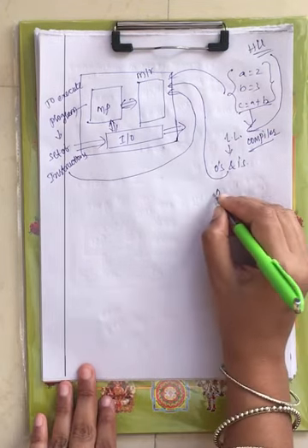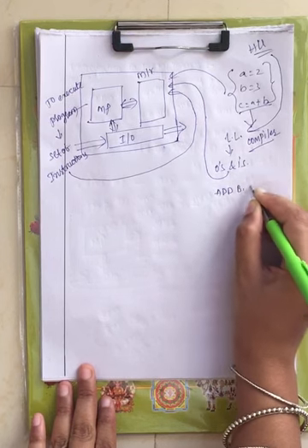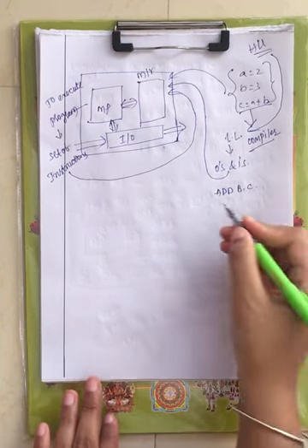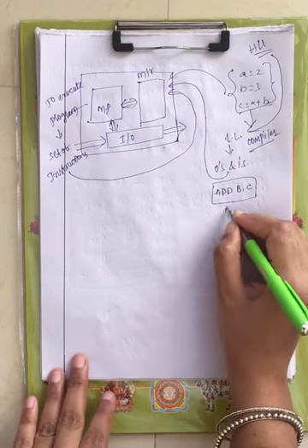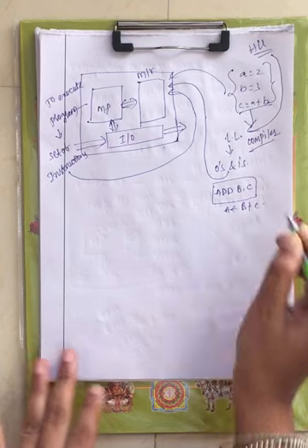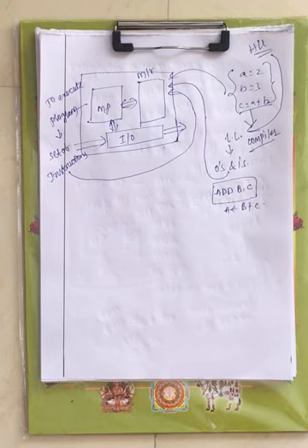Now this is one of the instructions under your microprocessor, ADD B comma C, right? Meanwhile just remember, if you see that instruction you will have a clear idea. ADD B comma C, what it will do, it will add the contents of B with the contents of C, right? Now where you will store A, you will have a register. These are register B, register C, register A. Later we will see that while discussing the instruction set. Meanwhile remember, this is one of the instructions under your microprocessor.